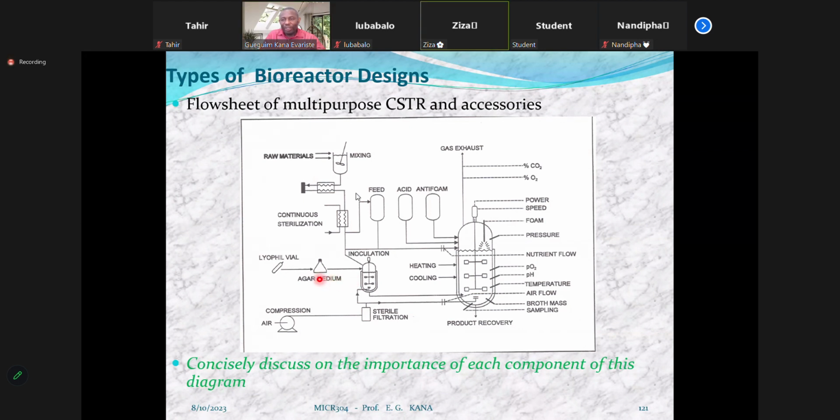Because Clostridium, which is involved in the production of hydrogen, can form spores that will withstand 100 degrees. By heating the source of inoculum, you remove the methanogens and other organisms that may be available, with the knowledge that the main organism that you want to produce hydrogen will survive that temperature. That cannot be considered as inoculum sterilization.